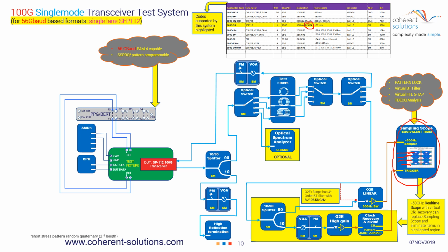Again, on an equivalent time scope, such as a Tektronix CSA 8300, in order to accomplish this filtering, you must be triggering the scope with a known pattern and have a recovered clock or the original clock with low jitter from the pattern generator.